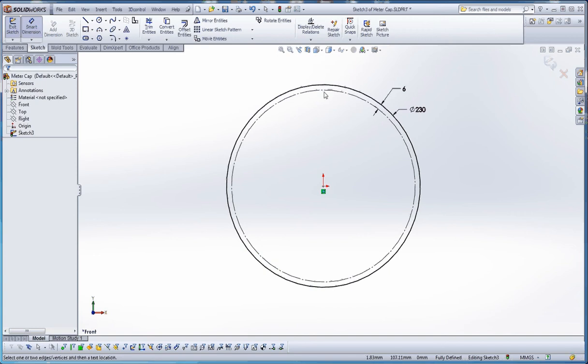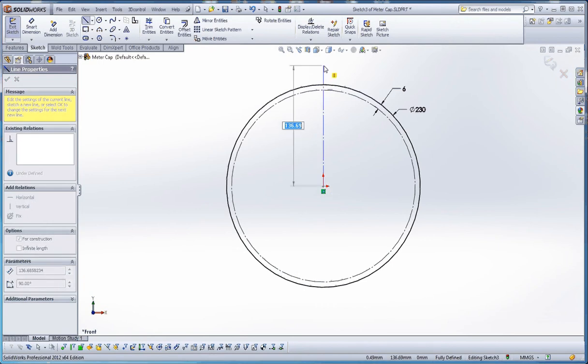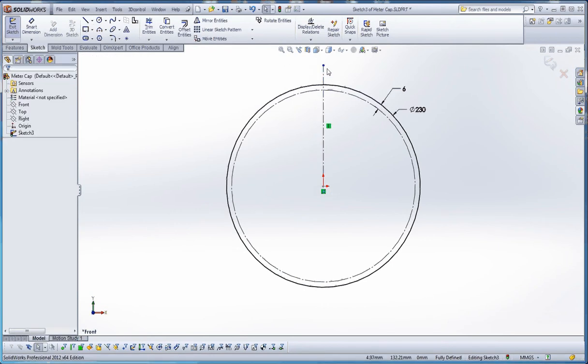So what we're going to be doing is drawing that tab off to the side. If we think about the cycle here, if we take 360 degrees and divide that into 5 equal units, that comes out to about 72 degrees for each unit. But if we go one cycle, if you were to draw a center line maybe north of that, the way you do that is you go up to the line command up here, go to the pull down arrow and pick out center line. And if you just draw that vertical, it'll be a black line, so with the blue point on top.